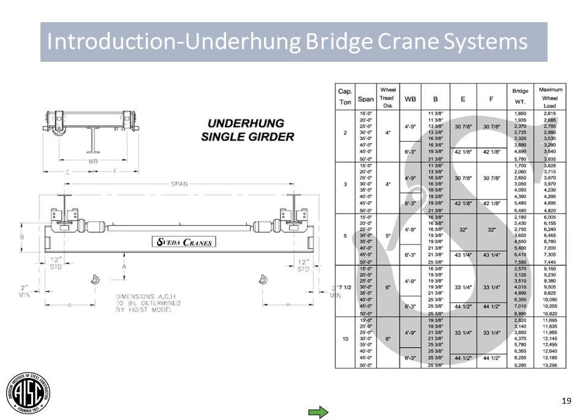Typical crane information that's provided from a supplier. This is from one specific supplier. There are a number of suppliers out there, but I wanted to just include this for your reference. There's a very large amount of information that can be provided by a crane manufacturer if you are able to get them on board early on in a project. Some critical information that you can find on these drawings would be the maximum wheel load. This is the maximum load that you're going to need to design for at every wheel of the end truck.